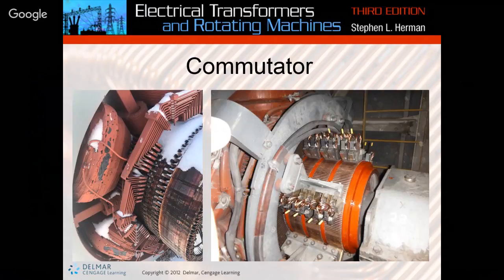So you can see in here, this thing has got a bunch of little lines through it. That's in order to only allow that certain amount of space to conduct. And what's in between, that white stuff in there, is called mica. It's like an insulator. And then this one is one that's actually working in the machine right now. Here's one that was right on the back of the yard as well. So see the difference. That's the nice shiny part right here.